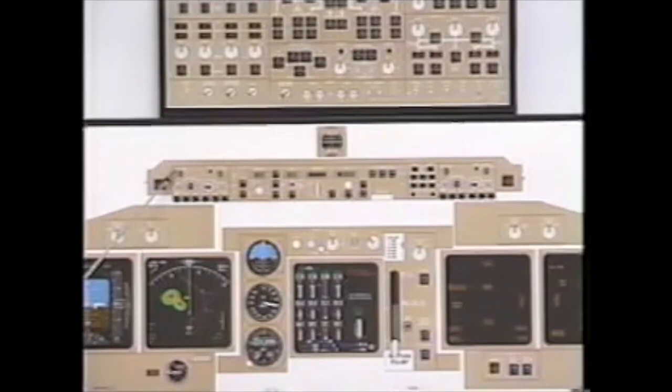To change the display, specifically for decision height or MDA, select the mode in which you wish to deal with. The small knob on top will increase or decrease that value. To get rid of a decision height, select decision height, turn it counterclockwise to indicate something below 0. That will blank the radio altitude display. To get rid of an MDA, select MDA, turn the selector counterclockwise below minus 100 feet to blank the MDA display. Meters button: meters allows you to display the meters equivalent of your actual and target altitude. It does not replace it. Pushing the meters button again removes that display.